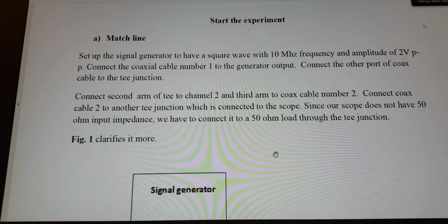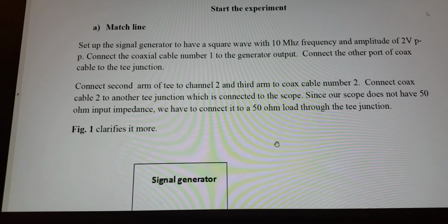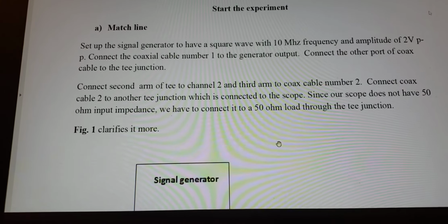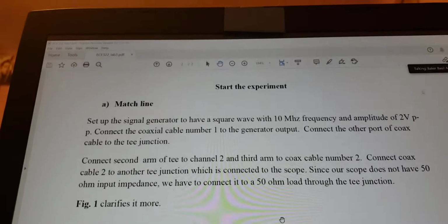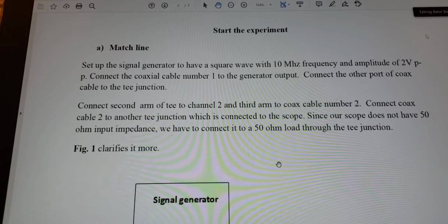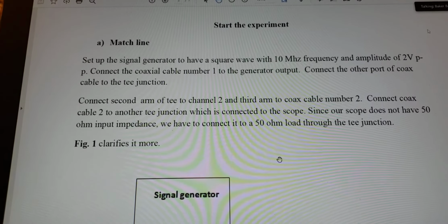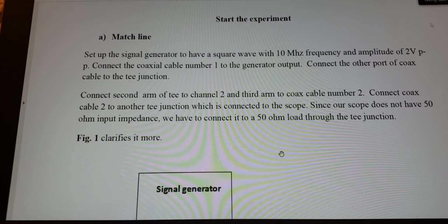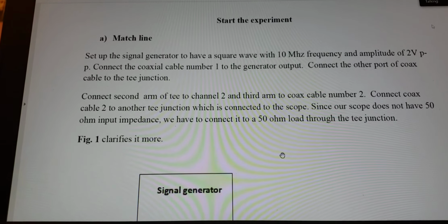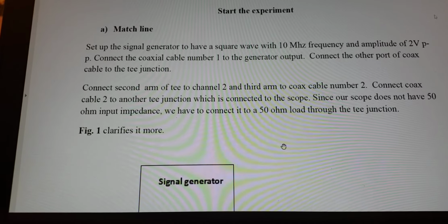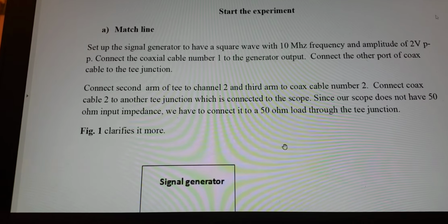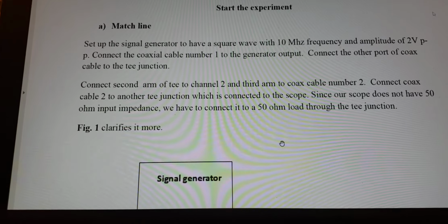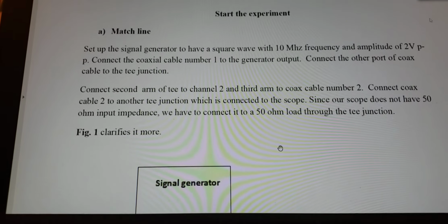You will not find distortion at this terminal exactly. You will find it everywhere in the line, because in this case, what do we have? We will have two signals in the line. One is transmitted, which we already transmitted, and we want to send it to the receiver side, and the other one is reflected, which comes from the receiver to the transmitter. So at any point now in the line, we will have two signals. We have the transmitted and the reflected, or we say the incident and the reflected, okay?